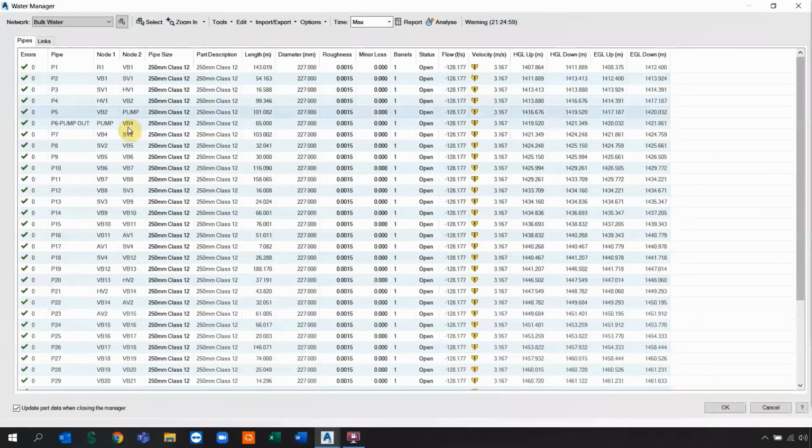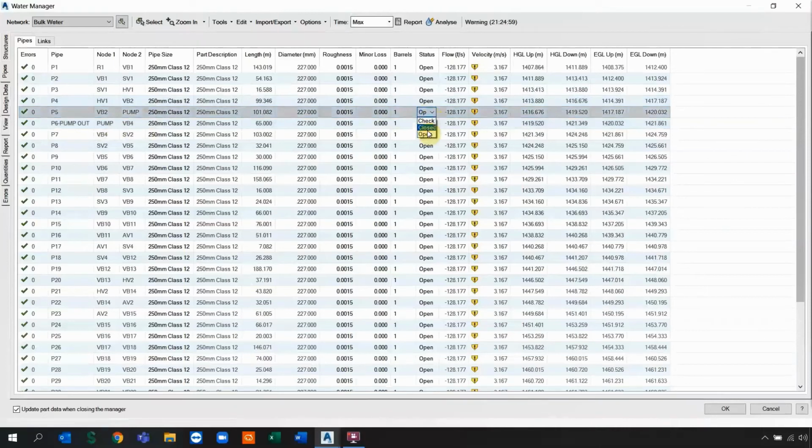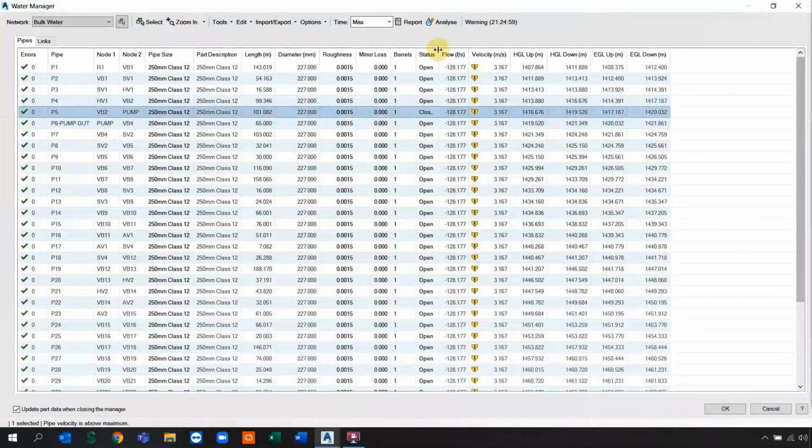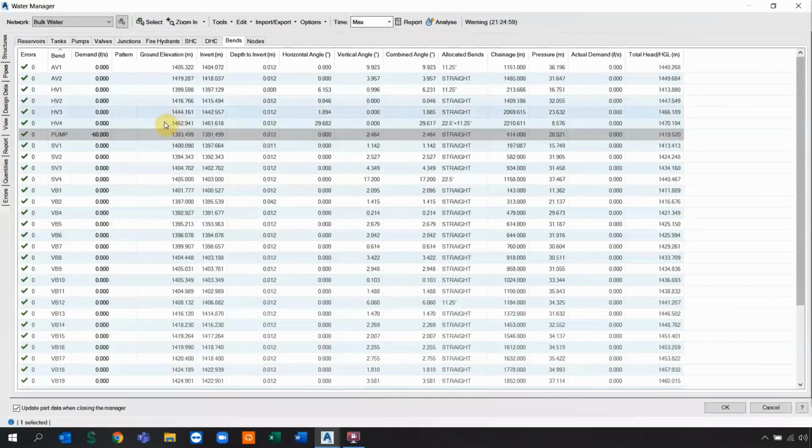And then something I need to make sure of is inside of the pipes, the pipe out, which we just marked, I need to close it, because it's going to allow me to run an analysis, and it will tell me exactly what my system curve is. And that's what I need to compare to an actual pump, which I normally get from my manufacturers and so on. So I need to close the pipe before the pump, or in this case, the junction, which we said is a pump.